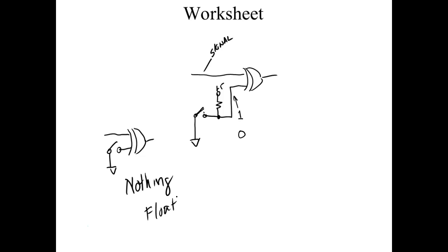So you'll see a lot of switches used in digital, but they're going to do it like this. They're not going to do it like this. If I open that switch, I get a nothing. I don't get a high. I don't get a low. Because a low is 0 volts. It's not a nothing. It's 0 volts, right? You understand? And when I open the switch, here we don't know. We don't have any idea what this thing is going to accept as a nothing.